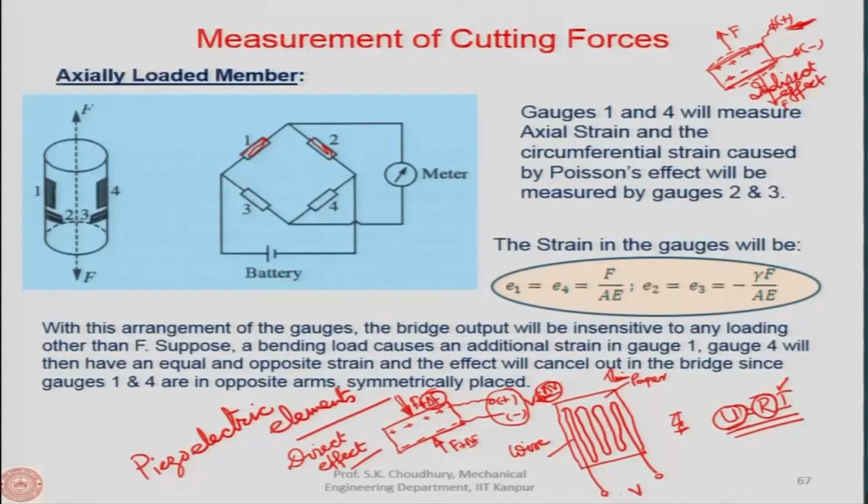So, this high frequency vibration can be created by using this indirect effect of the piezo elements, when the current is passed and the whole thing is expanding. Now, if you are changing the frequency of the current, at that frequency it will expand and come back.